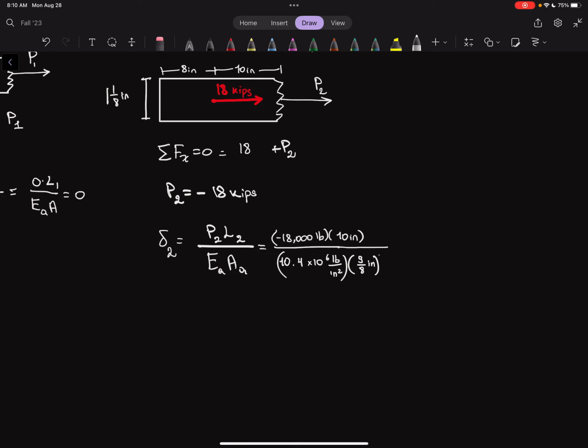And that's the diameter. So if we square the diameter, remember to divide pi by 4, because it's the same thing as having the diameter divided by 2 inside the square, but then taking out the 2, and it becomes a 4. So once we do that, and we plug in everything into the calculator, we get negative 0.017412 inches. And those are the inches of deformation.